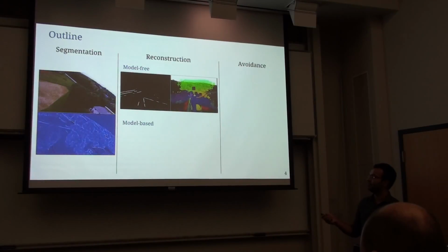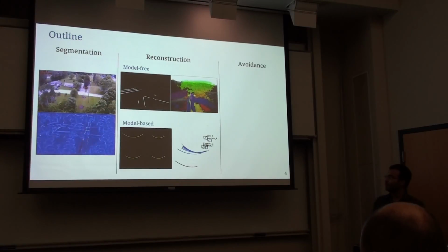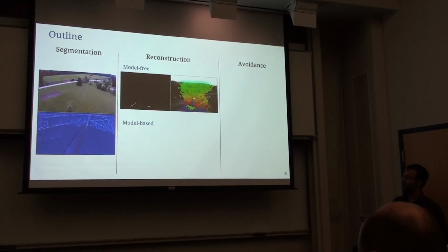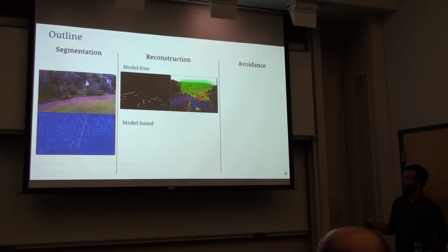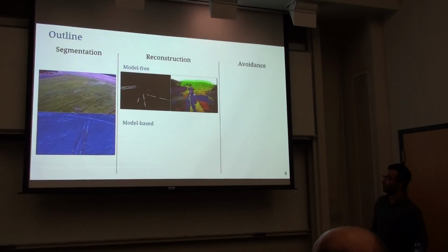And this is an efficient way of doing that, just using images. So we'll talk about this in detail. Here you can see an inspection task in which you are seeing missed detections, and you can reconstruct them with those blue and purple voxels. And the things in the background are actually just observed by the stereo camera.